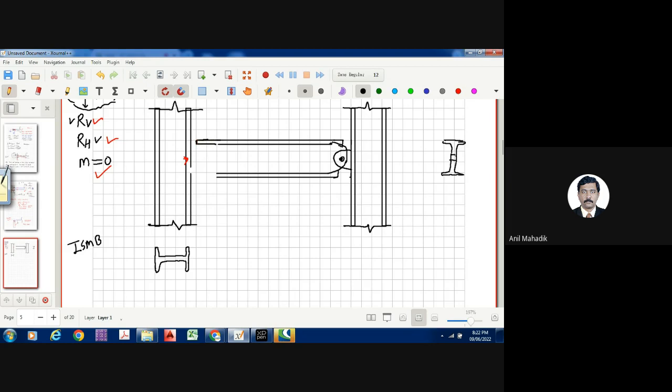Then I am cutting this flange. ये flange है नहीं, this flange. I am not taking this till this end. And then web, a small web portion I will cut it. Okay, and यहाँ I will put bolting arrangement. यहाँ plate करूँगा ऐसे and I will put one bolt over here, right?